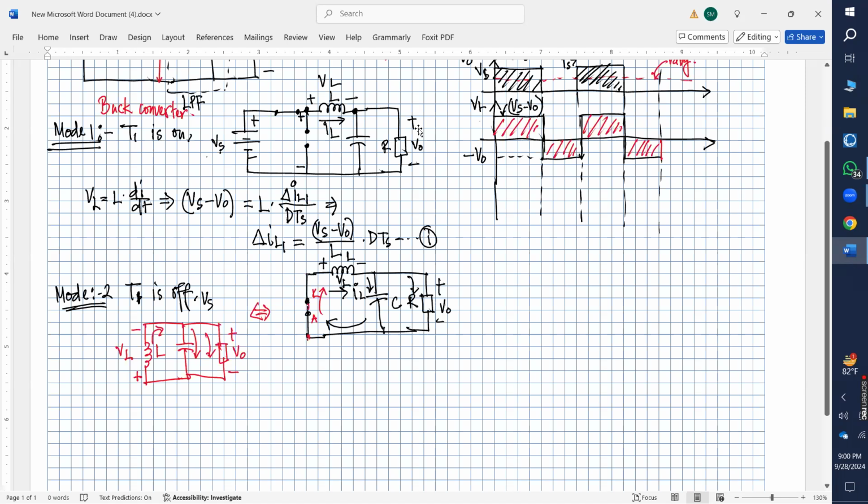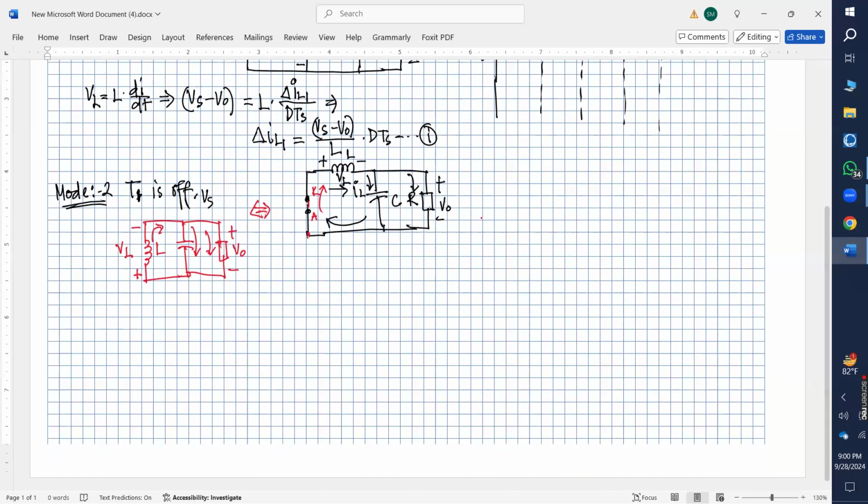Sir, he asked what is the function of the low-pass filter here? Okay, so this is my low-pass filter, right? And before the low-pass filter, when you have a switch, the output here between terminals A and B would be a pulsating DC, instead of the purely DC that the source is providing, right?